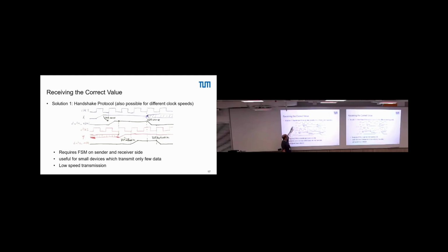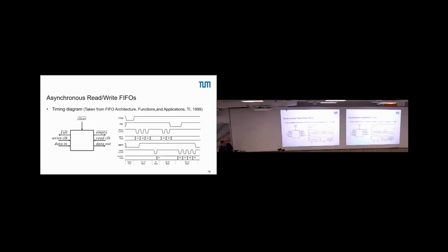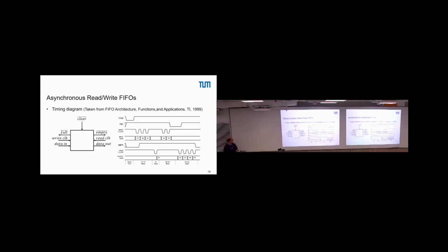And your data here can, with the synchronizer on the previous slide, come in arbitrary size. So, problem at that point solved. An alternative to that, or effectively bringing together this handshake protocol with such synchronization at the end, brings us then to these FIFOs.